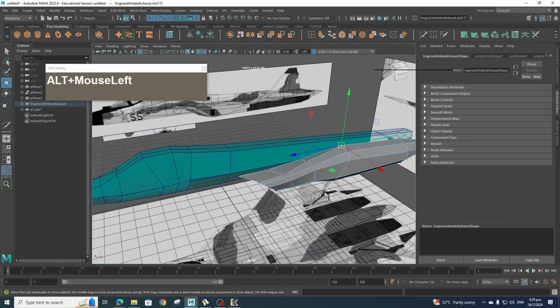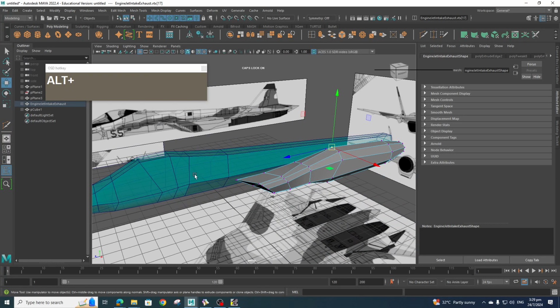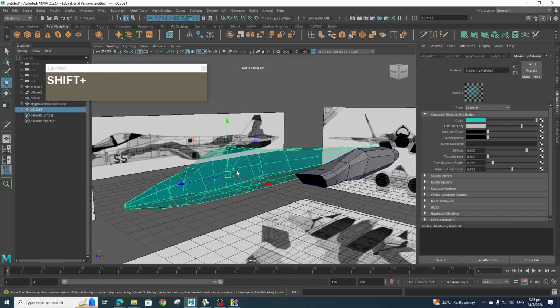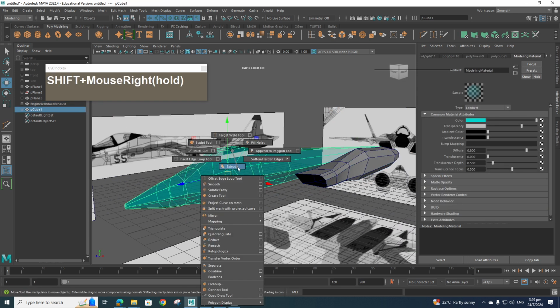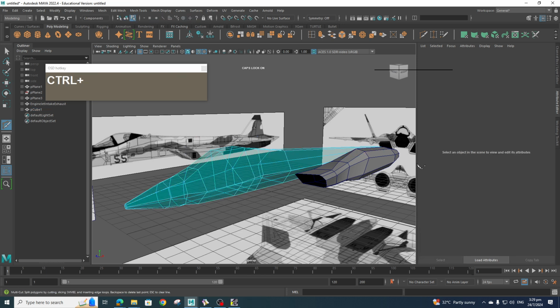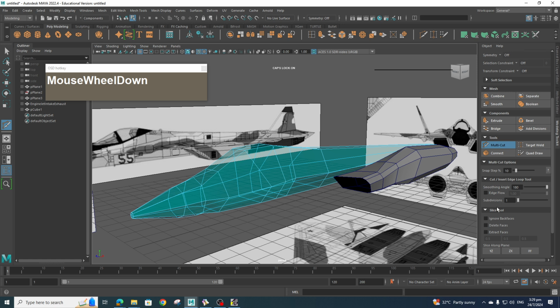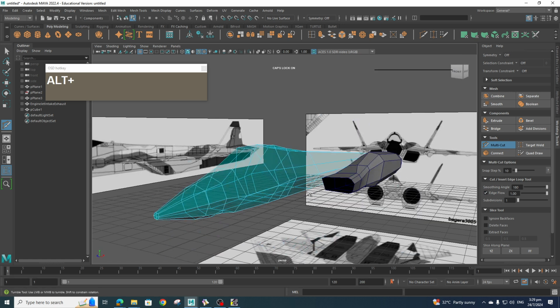Okay, so now for the wing, I'm probably going to pull it from this side here. That means at this stage here, I'll have to add in a couple more subdivisions. So I will insert an edge loop. Now before I do that, I'm going to enable the edge flow and see whether that helps to puff up the sides a little bit. So I'm going to middle mouse click here.